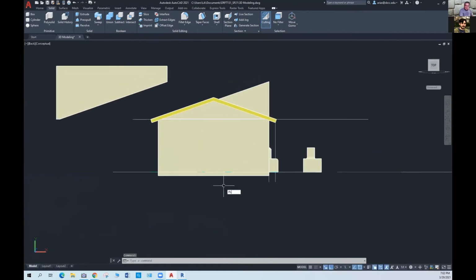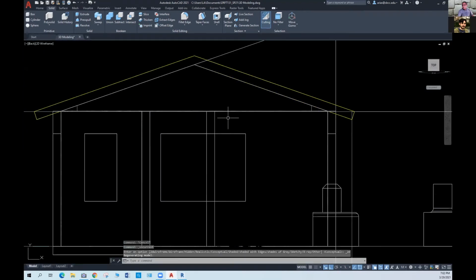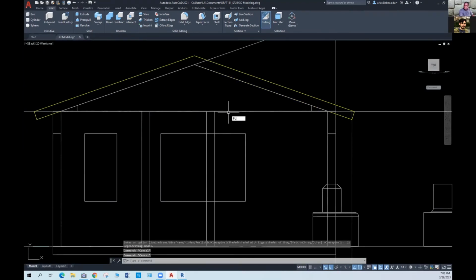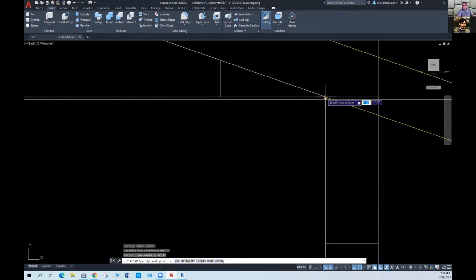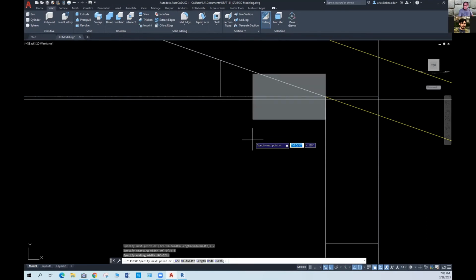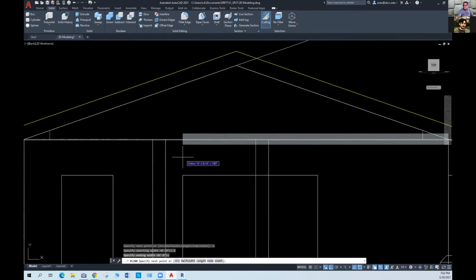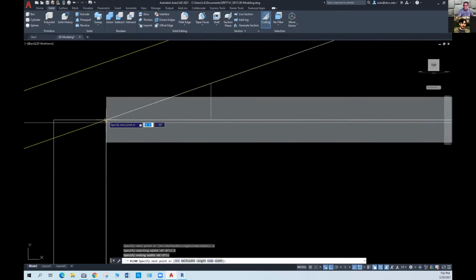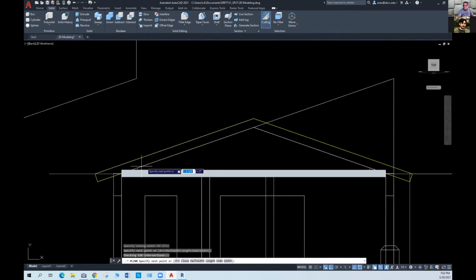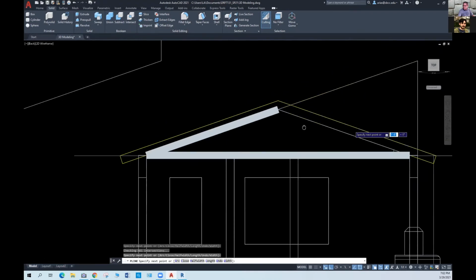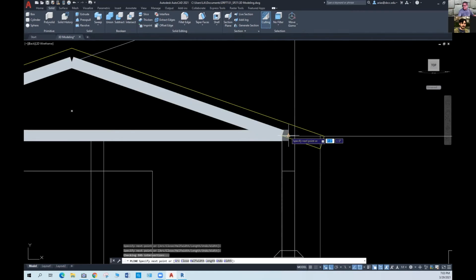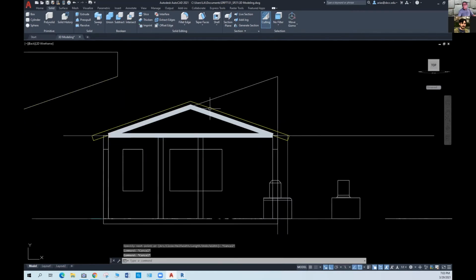So I can do a polyline. And maybe what I do is I select wireframe. I'm going to do a polyline that connects all of those points, right? From here, maybe do a width that I can see. That's a pretty thick polyline, but that's fine. 1. And then from that point to here and to there. So I just created that polyline.